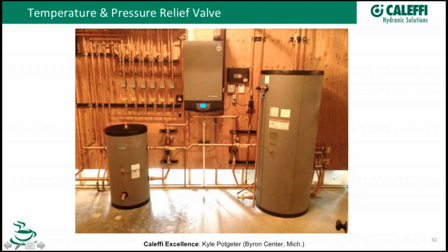I think theoretically the manufacturer wants you to test these yearly, pull the lever on it, make sure that they discharge. What you're going to find if you do test them, sometimes you'll pull the lever, yeah, they discharge, but then they don't shut off and you're replacing it. So just plan on having one with you if you're going to start pulling relief valves and checking them for discharge. There's a good chance it might not shut off and you're going to replace it anyways.